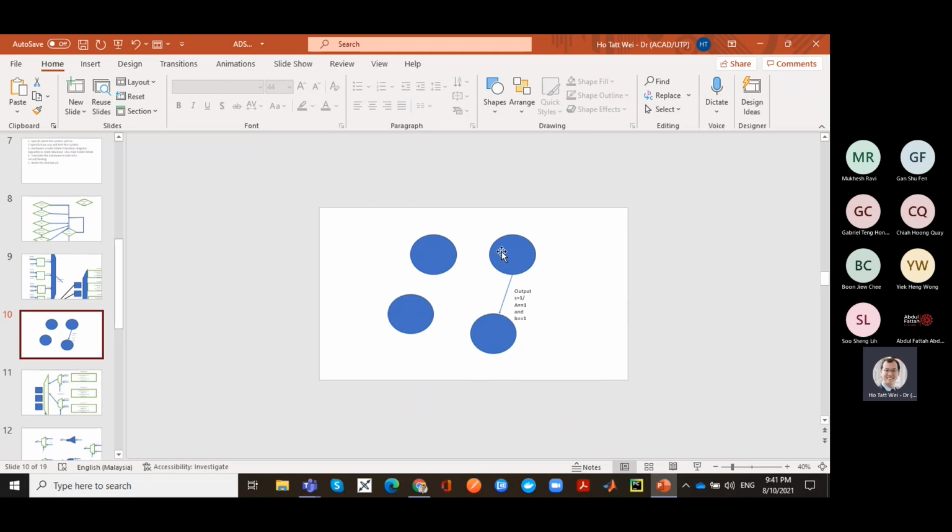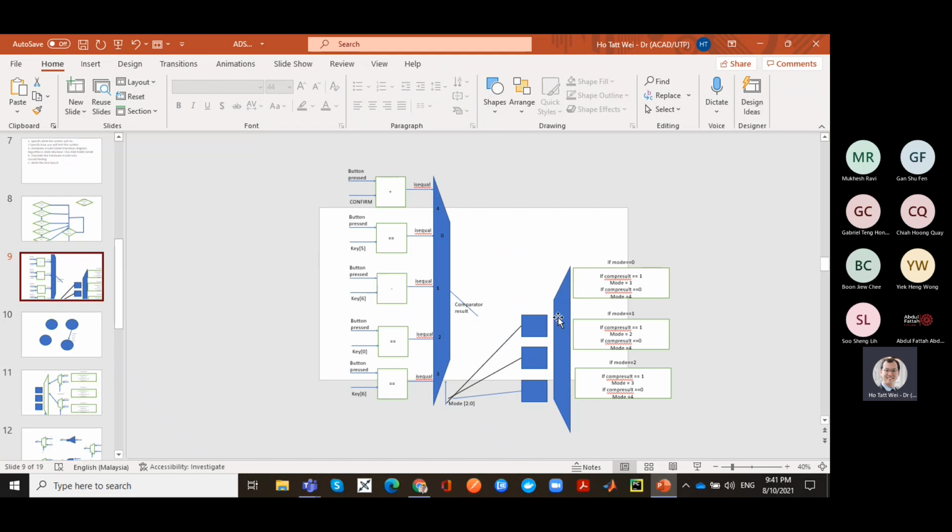And you have arrows that tell how you progress from one mode to another. If there's nothing on those arrows, it means that every clock cycle it just goes to the next mode. But usually you have certain input conditions that allow you to transition to that mode, and if you don't have that condition, you go into another mode. So a state machine is nothing else but explaining how you progress through the sequence of modes, and then you have to figure out what the outputs are at each mode. And that's actually the computation that you need to do.